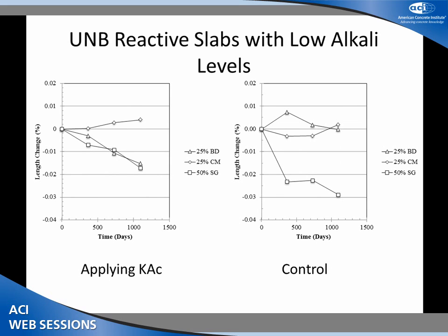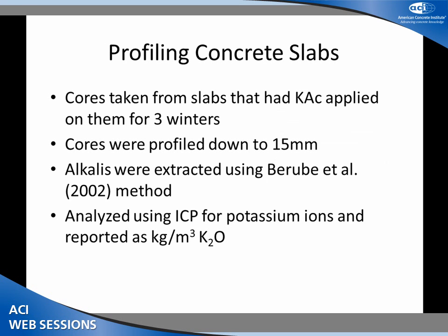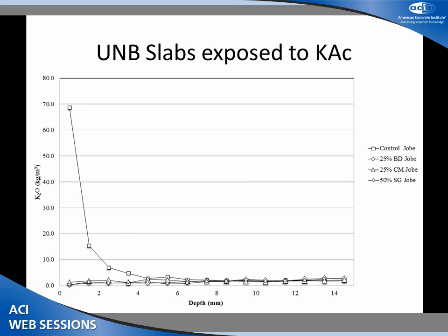This is just showing the application of potassium acetate on these reactive slabs that have low alkali levels. Since the other ones haven't gone yet, I wouldn't expect these to go yet. What Sean did was he took cores from these slabs after 3 years, and he profiled down to 15 millimeters, and then he analyzed them to see how far in the actual potassium has gotten into the slabs.